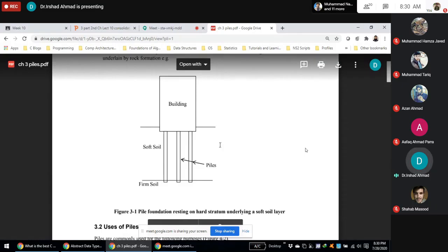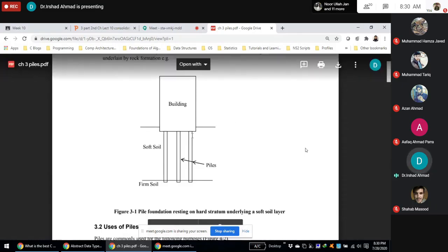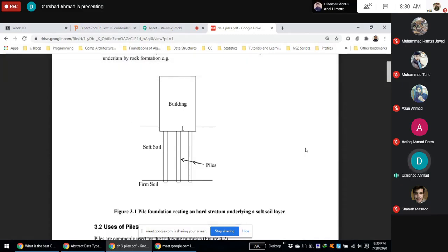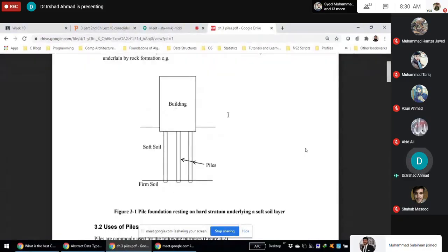Nalas or rivers under a bridge foundation lead to scouring. So if you provide a shallow foundation, the scouring can cause erosion and the foundation would be undermined. So in that case, we provide piles so that if there is some erosion, no problem. There is sufficient length embedded into the soil, which gives you the capacity, right?